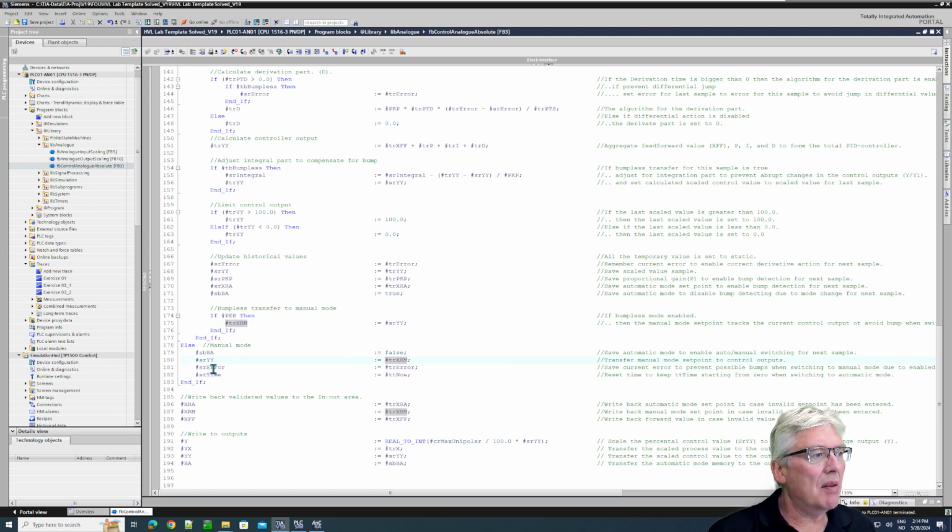And my error, just to prepare. So this error I had the last time, the static error that I have saved, is error now. And as the time is t2 now. And here for the error, we could have used an error with a k index and a k-1 index to indicate that this one is the error that I had the last time. And I could use that also for these values here too. So it could be refined a little. And what I do here is scale the output to the Siemens analog value range and so on. And I update the outputs here.